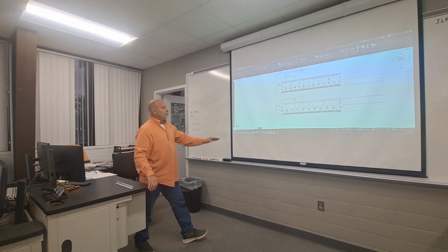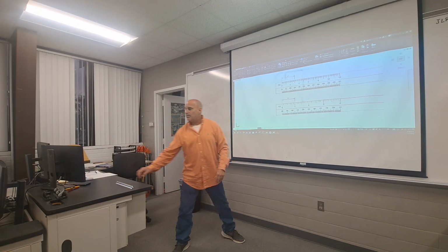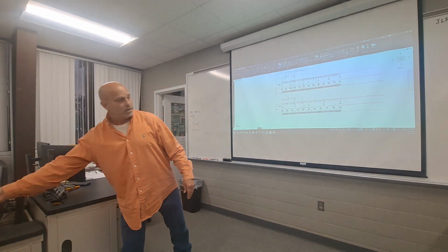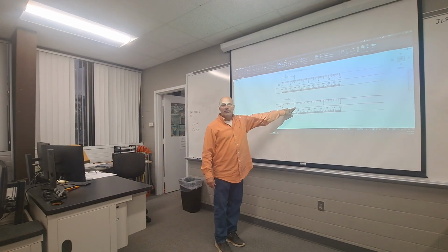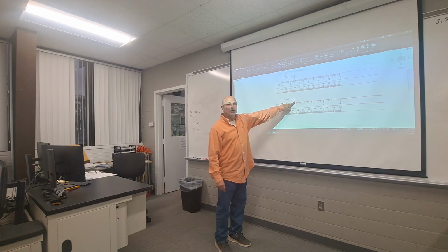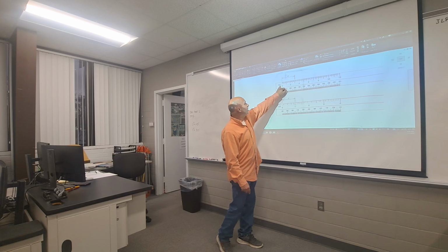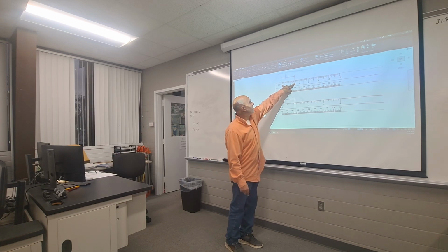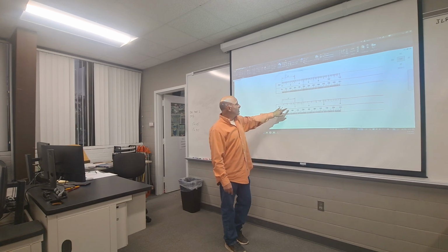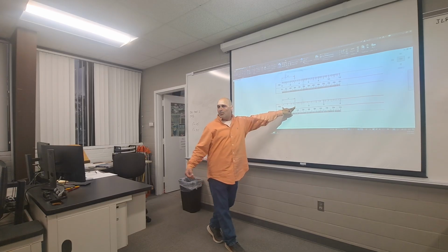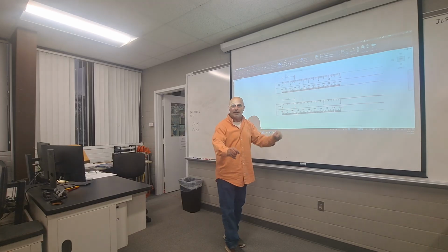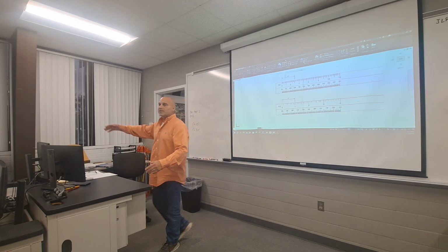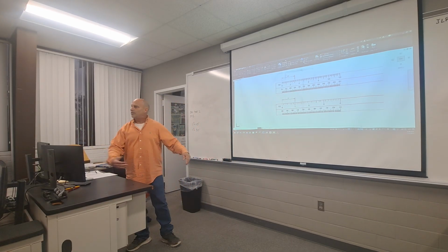On this scale, where it says the 10 on the end, and if somebody close needs one, y'all can look at mine. This number 1 right here that you see, if you were to get a regular ruler out, you would see that the distance from 0 to the number 1 is 1 inch. Up here on the 30, the distance from the 0 to that line right there is 1 inch. So that tells us that in a drawing that is scaled 1 inch equals 10 feet, if I put a regular ruler up there, I can say, all right, that's 1 inch long, that's 10 feet. Build that sidewalk 10 foot long, and then we turn.